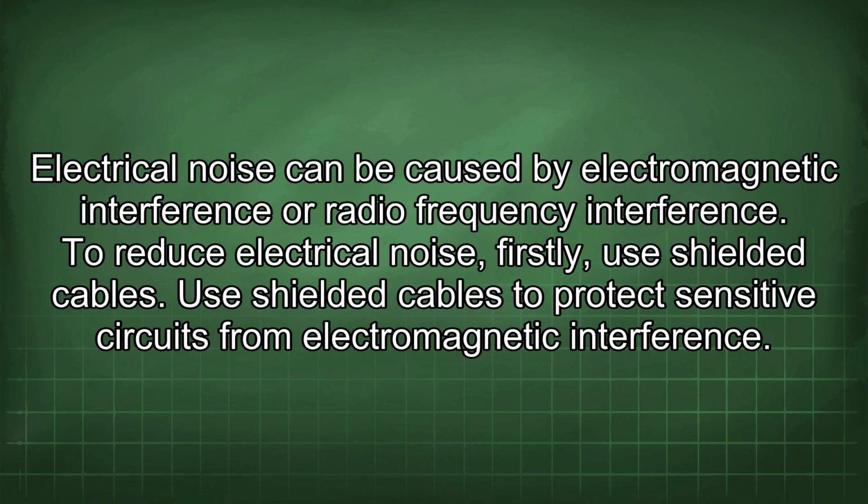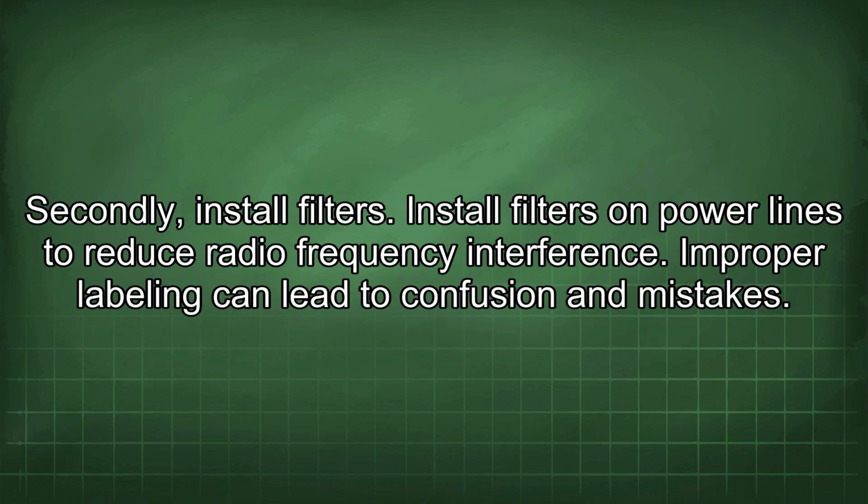To reduce electrical noise, firstly, use shielded cables. Use shielded cables to protect sensitive circuits from electromagnetic interference. Secondly, install filters. Install filters on power lines to reduce radio frequency interference.